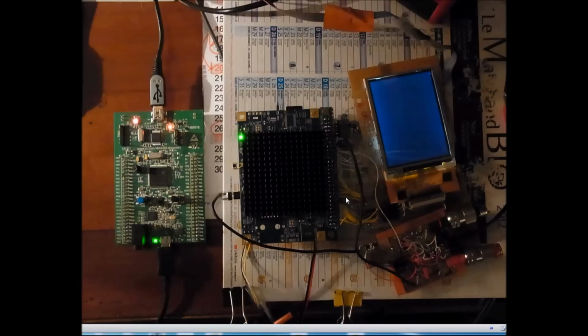The Zynq is fast, very fast. I use the pi-digit calculation method to compare the speed of interpreted code running first on the STM Discovery 4 kit with a 168 MHz clock, and then on the Xilinx Zynq with a 667 MHz clock. For both, the code is built with the exact same GCC version, respectively for the Cortex-M4 and the Cortex-A9.